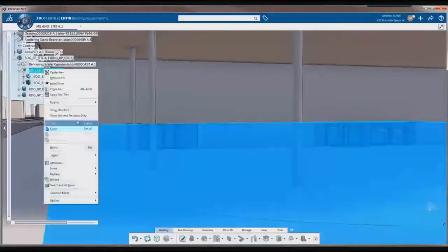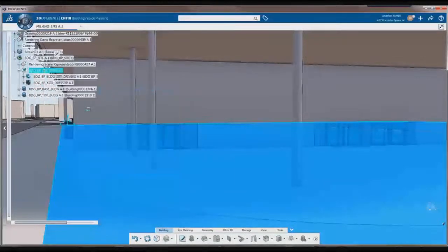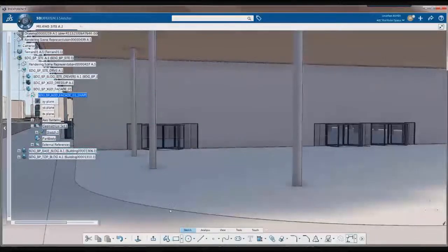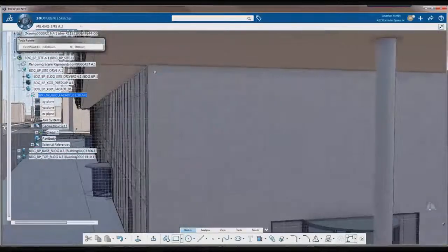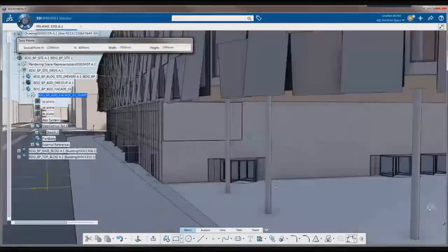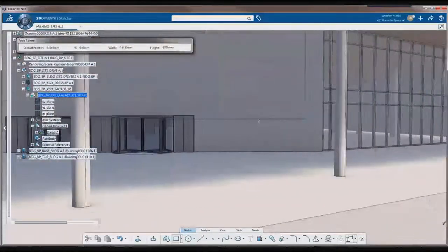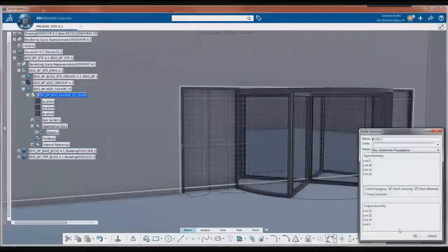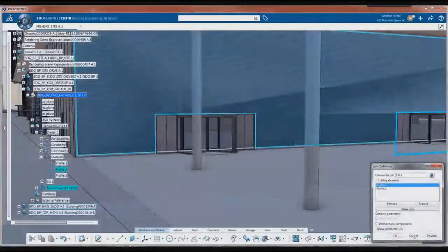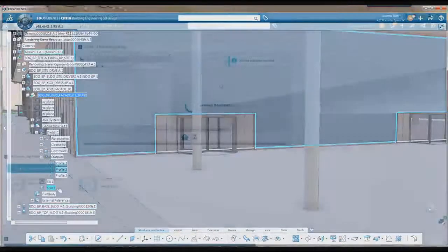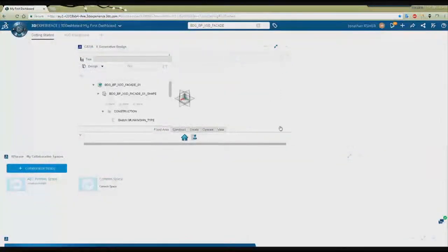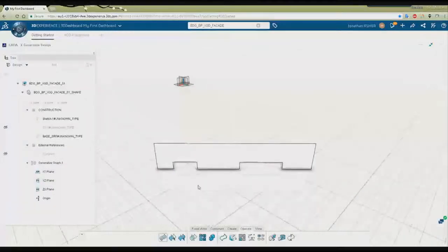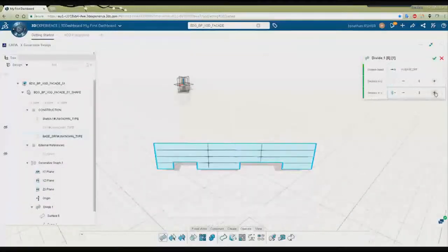This video is the collaborative feature wall video, where we're starting in CATIA on the rich client that you've installed on your machine. We're going to insert a new part into the model and use the CATIA sketcher to create a surface. So right now we're in the sketcher. We're going to make a quick surface. We're going to make a rectangle. We're going to output that profile curve. We're going to also create curves that define the boundaries of our doors. We'll make a surface. We'll split that surface. We'll save that file. And then we'll go to X generative design on the web, search our collaborative space, find that file, find that part, and open it in X generative design.